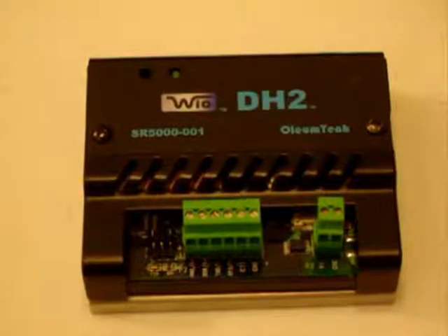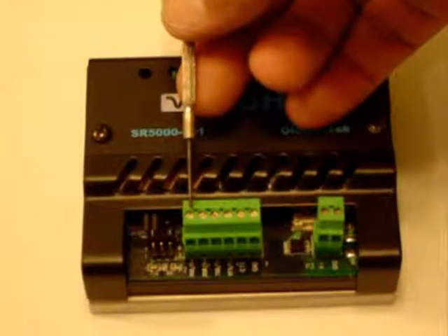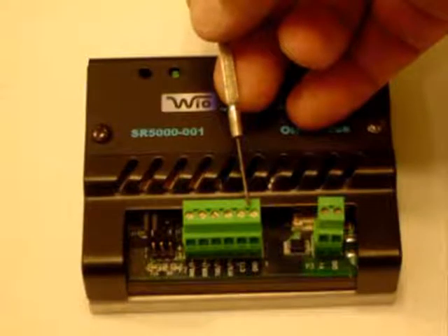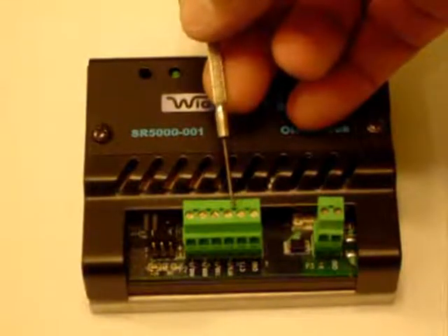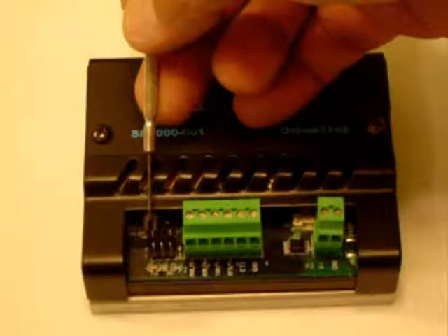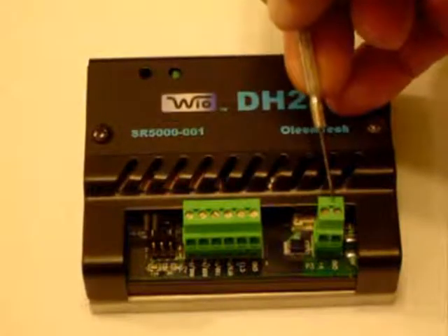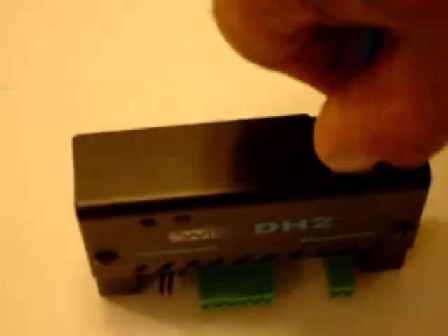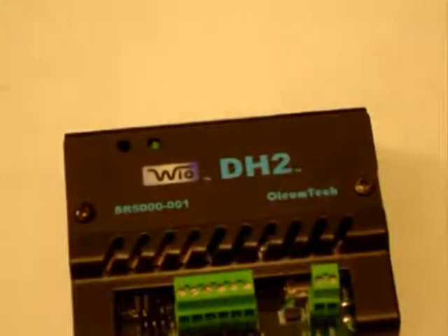The connections for the DH2 are a Phoenix connector in the front for 232 or 485 communication wiring to interface to your Modbus master. You also have jumpers beside this connector that must be installed if using RS-485. You also have a power and ground connection. On the back of the DH2, you have your configuration port, an RJ jack, which is used to download your configuration from Breeze. On this side of the DH2, you have an MMCX connector, which is used to connect your antenna. And that is all the connections of the DH2.